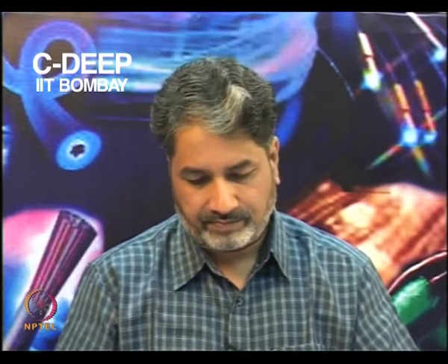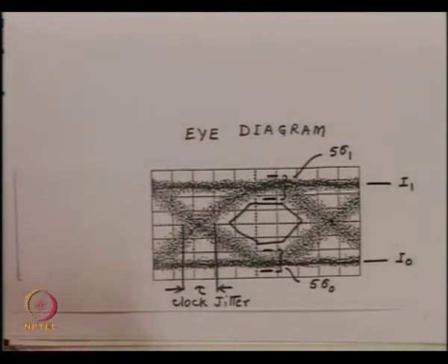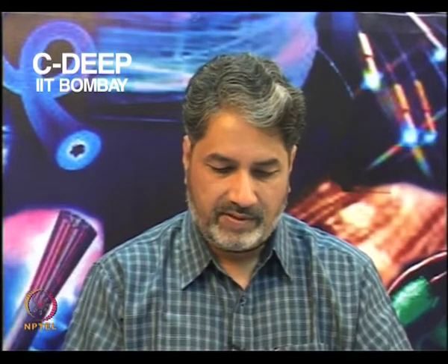And when any of these situations happen inside a receiver, you have performance deterioration. So, the eye diagram is one of the very important diagrams. After the system is designed completely and commissioned, one has to perform the final test on the data, which is the eye diagram, and only then can one satisfactorily say that the optical receiver is performing satisfactorily. So, these are certain tests which are conducted on an optical receiver, and the parameters are extracted to calculate the quantitative parameter called the bit error rate.